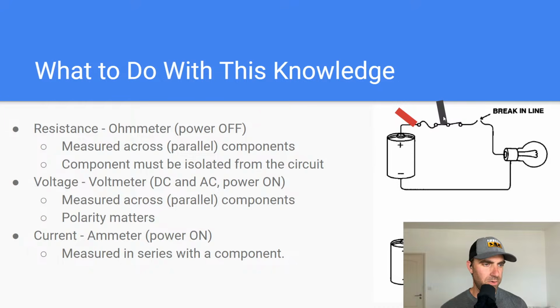And so with reference to ground, you would be looking to see whatever the expected voltage was at this point. If you were expecting 12 volts here, and you wanted to make sure that power was on and available here, you would check for 12 volts. So the red probe would go here, and then your black probe would go to the airframe ground. Your black lead is essentially creating the path back to ground for your voltmeter to register.